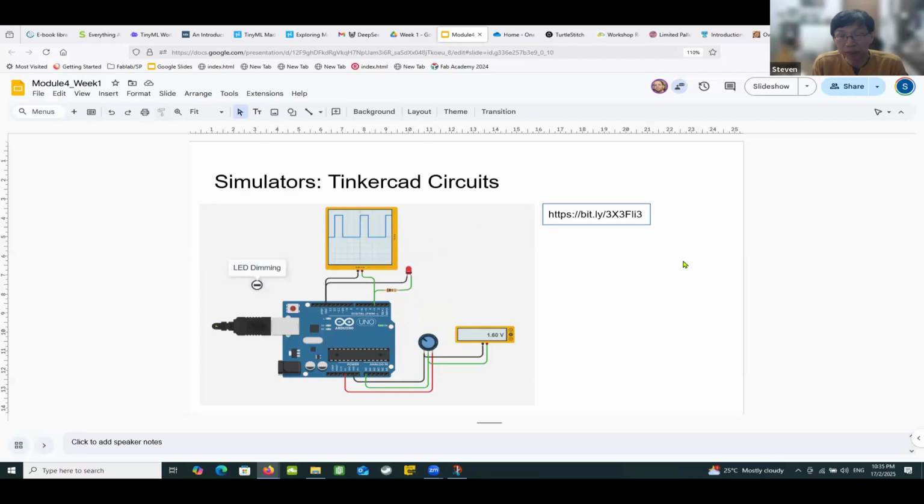And the way that we do this in this case here, because the output is either a 1 or 0, so either 5 or 0, but you can control the light intensity by using a technique called PWM, pulse width modulation. By changing the width of the pulse, you can change the light intensity, because essentially you're sending an average voltage to the LED. Of course, where you can put an LED, you can put in a transistor or FET device, or use a relay to turn on a higher voltage light source, or even an AC light bulb or appliance.